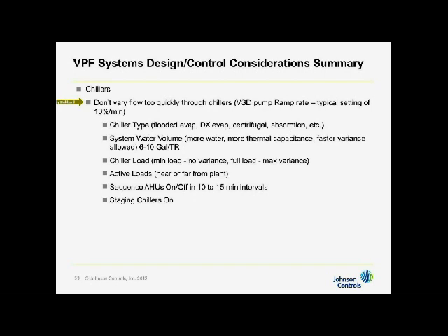Okay? Now, the type of chiller can change how much and how fast you can vary flow. Flooded evap, DX, centrifugal, absorption. Absorption maybe 3% per minute if you're lucky. But centrifugals with flooded evaporators can handle the most. VPF, in case I should mention that, variable primary flow, if anyone doesn't know what I mean when I say VPF.